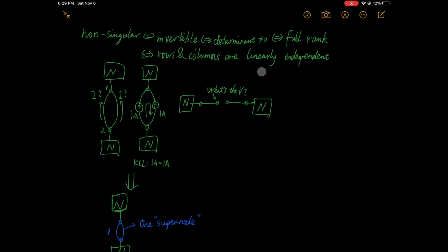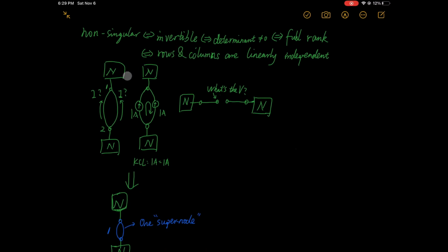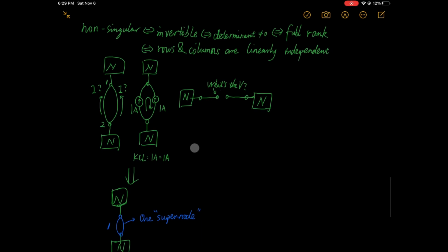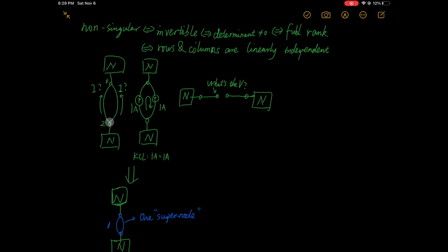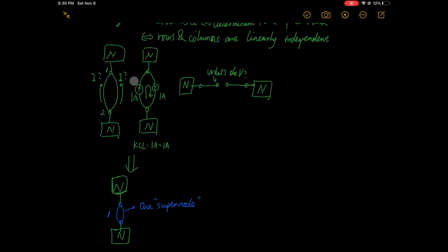This is generally true unless you have two parallel connected short-circuited lines, or parallel connection of two ideal inductors, or two ideal current sources, or you have two open-circuited lines in series, so there is a floating node. The result is that you have two nodes connected to the same set of branches in the same way. So the system is underdetermined and the Y matrix is singular.